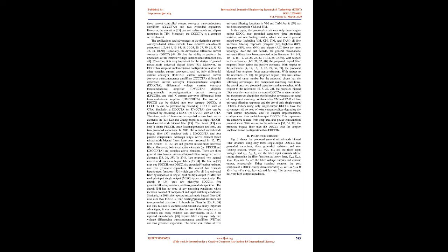Two digitally programmable mixed-mode universal biquad filters were proposed in [31], [32], which can achieve many main advantages. However, the filter in [31] uses two multi-output second-generation current conveyors, MOCCIIs, 6 digitally programmable second-generation current conveyors, DPCCIIs, i.e. 8 active elements, 4 grounded resistors and 2 grounded capacitors.